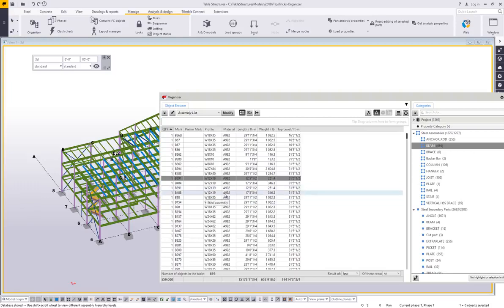When you have different people modeling and they're moving very quickly, you may model in a beam and forget to change the material grade to the correct grade. And you accidentally model in an 8x10 that's A36 or something goofy like that. Once you turn on the group, you can grab any one of these column headers and drag and drop it up to the grouping field.